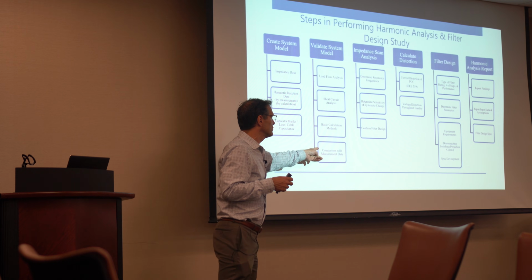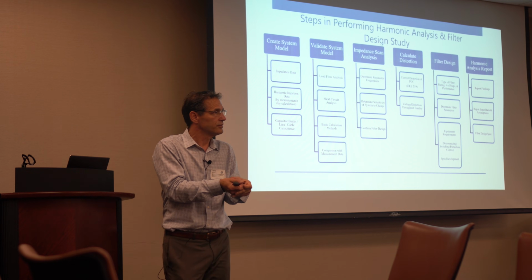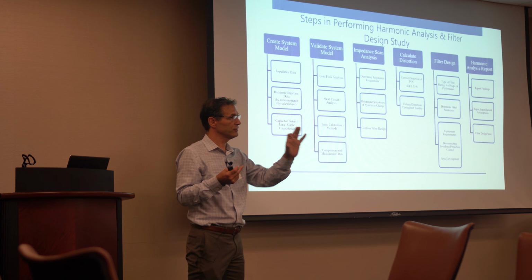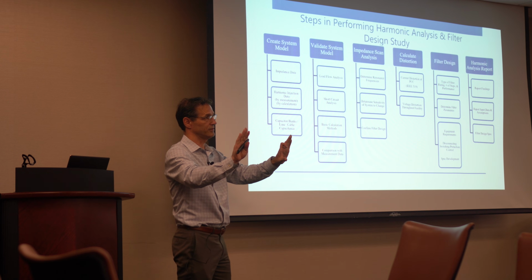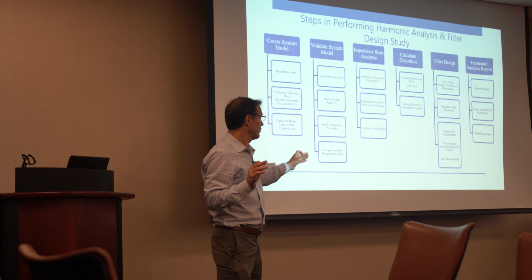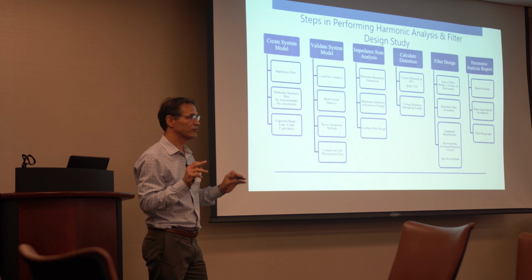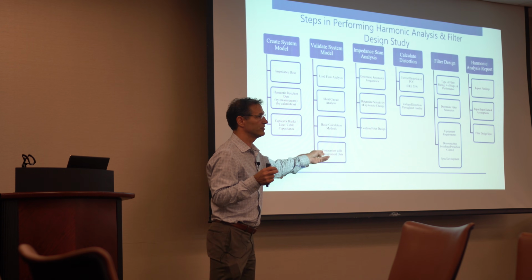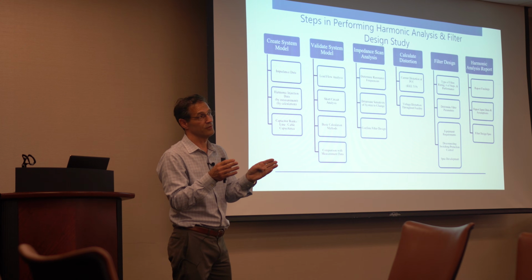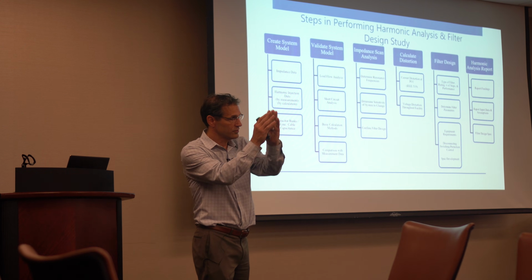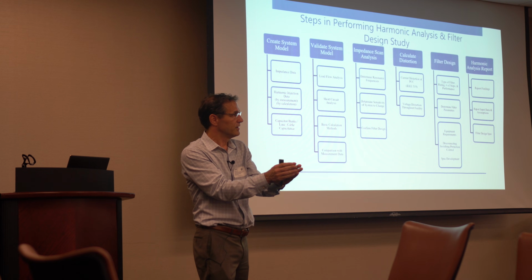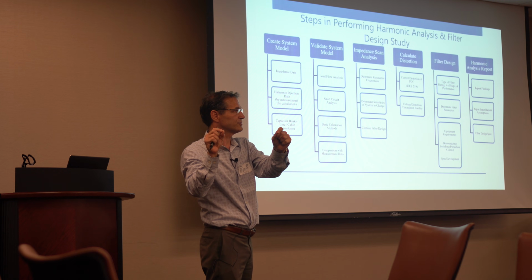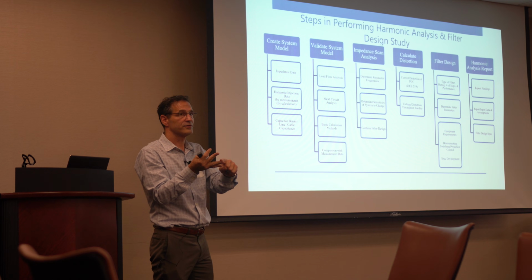There is an occasion where somebody might go out and take harmonic measurements, and you could take your harmonic injection data and put it into the model and compare that to your measurements. And I see that, and I used to try to do that, and that's really opening a can of worms, because when you try to match your analysis to your measurements. What I'm saying is somebody went out and took harmonic current measurements, they put that harmonic current measurement into their data file, and then they run the simulation and they calculate the corresponding voltage distortion at the bus. So you've got some value of fifth, some value of seventh, some value of 11th.